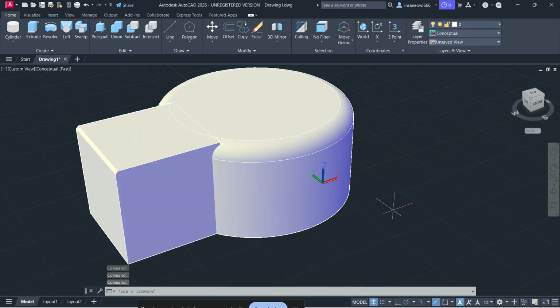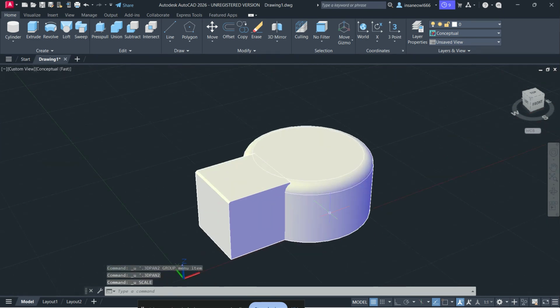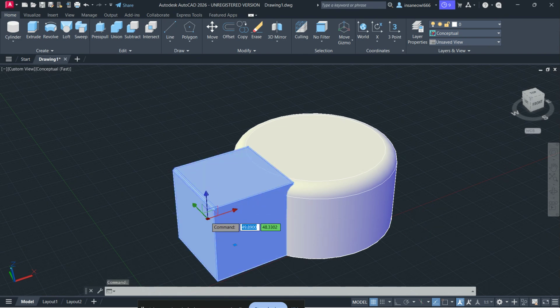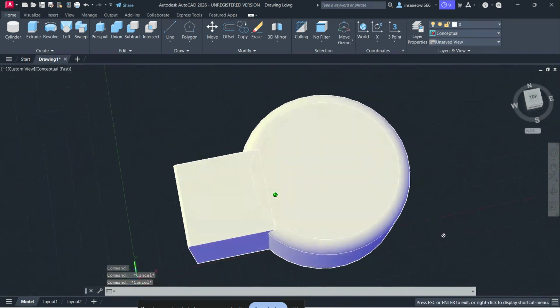So to recap, reduce the radius or offset, clean the body, check the validity of the solid, change the order of your operations, try a tiny micro move for Boolean issues, and scale the model up if needed. In many cases, one of these fixes will clear the error and let you finish the command without rebuilding the entire model.